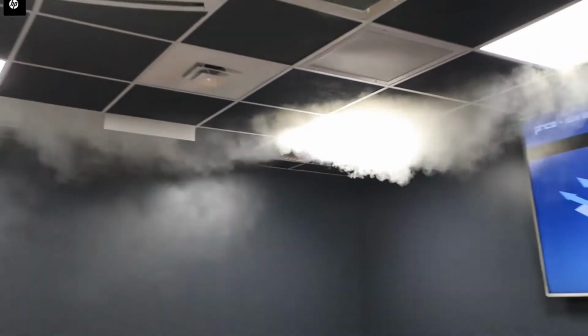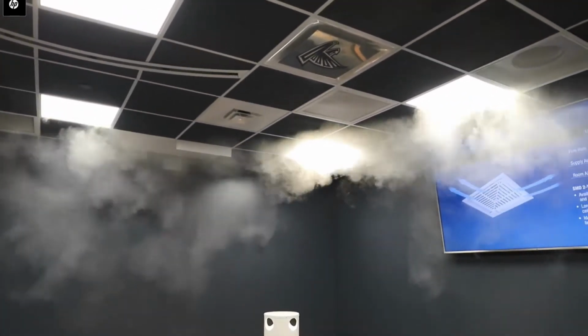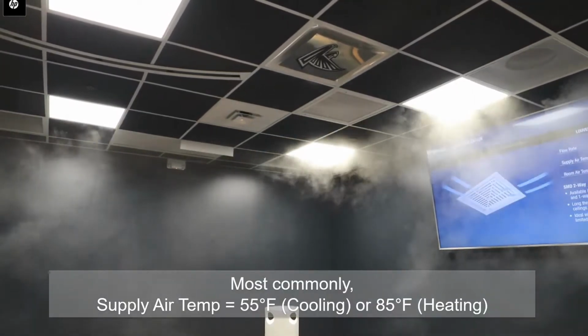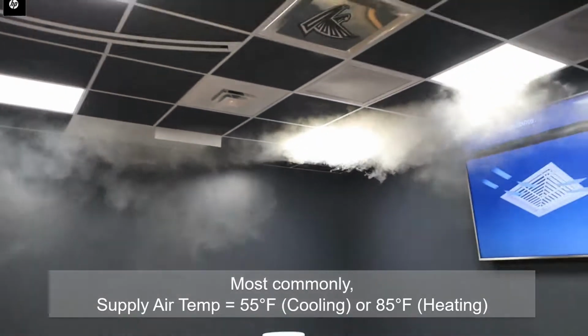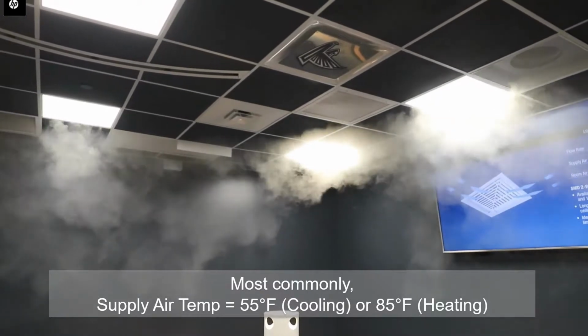There are several different diffusers, many different models, and all have different performance parameters. Typically speaking, we would supply our air at about 55 degrees Fahrenheit, though sometimes if we need to heat the room, we might supply the air at a warmer temperature, usually around 85 degrees Fahrenheit.